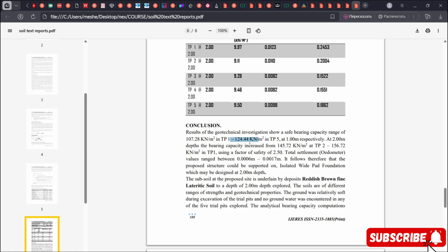So now, from that 1000 millimeter depth, they move on, because we have not gotten our allowable bearing capacity, which, like I said, is mostly 150. So they have now gone to 2 meter depth in the ground, and at that depth you see that the bearing capacity has increased from 145 at TP1 to 156 at TP2. They did not even go to TP5. If it was me, I will use 2 meter depth with 150 bearing capacity because it is safe. Do you understand?